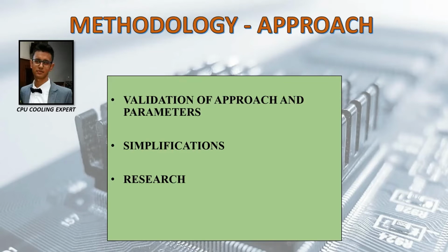Before getting into the simulation, the system and method needs to be validated. This was done by obtaining a simulated solution and analytical solution to a simple tube bank forced convection problem. The results yielded an error of less than 10% when a mesh value of 3 was used during a conjugate heat transfer simulation. Modeling a CPU is complex, so simplifications were made.